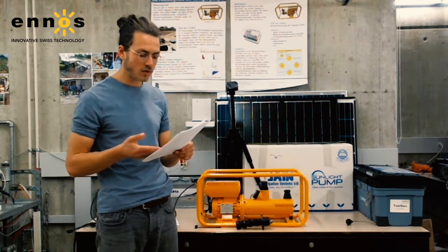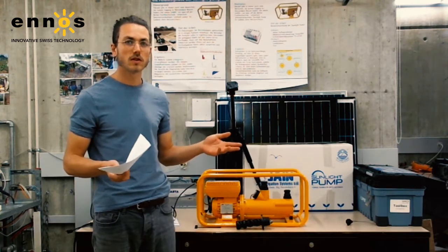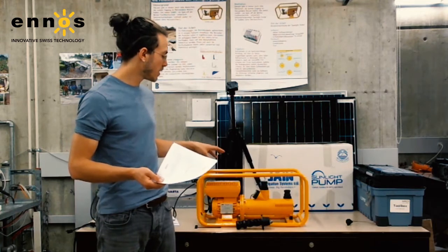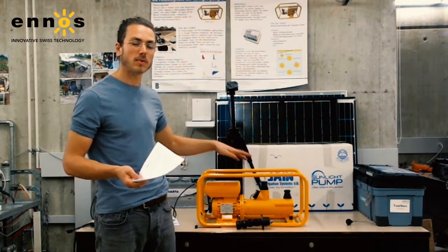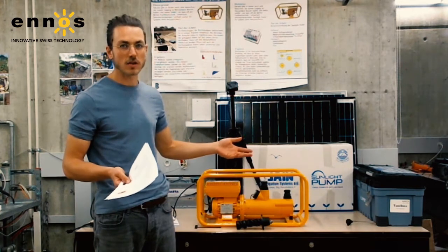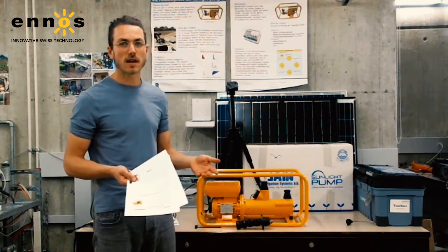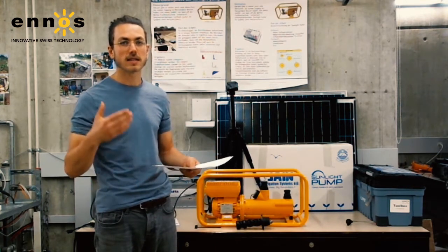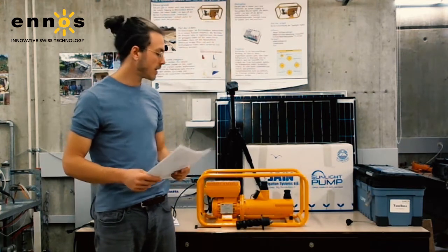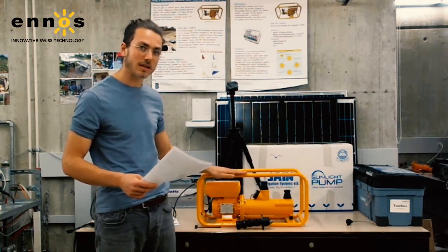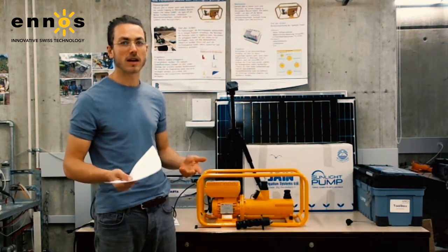You see the type of enclosure, IP65. This means it is sprinkler waterproof, so it's not bad if water gets onto the pump in small amounts, but you need to make sure that it is not submerged underneath water. This is a scenario that can happen when you've got it placed in a well or close to a water source with varying surface levels. And when the pump is submerged underneath water, it can take quite serious damage and will need repair or replacement.